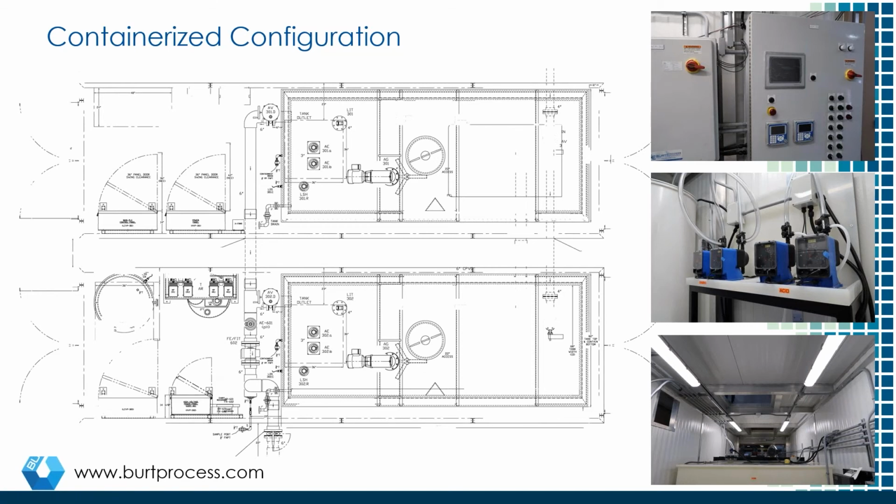Very often with these types of systems, you will have a segregated environmental control, and that can vary considerably based on the location of where you are and the requirements, exactly what you need. But generally, some kind of an air conditioning and heating based system. Obviously, in warmer climates, air conditioning is certainly more important. Putting a metallic box outside with the system, with the sun beating on it all day, can make that environment very warm for the operator. But at the same time, if you're where I live up here in the northeastern part of the U.S., we have a lot of concerns about freeze protection, snow loading on the systems. That kind of all comes into play here as well.